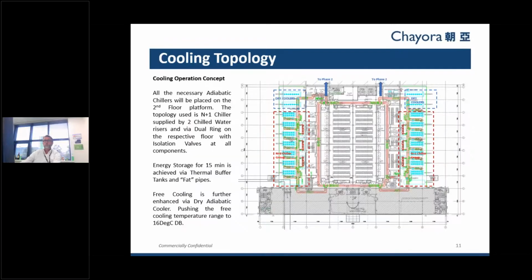Okay, our cooling systems. It's not showing the slide, but we employ wall fans in our data halls. The wall fans are fed from both a chilled water system and a dry cooler system. The majority of the cooling is actually done by the dry cooler. I call it the economical feeder, where we use the ambient air to cool down a bit, and the chiller systems act more like trim cooling, which cools the data centers to the desired temperature.